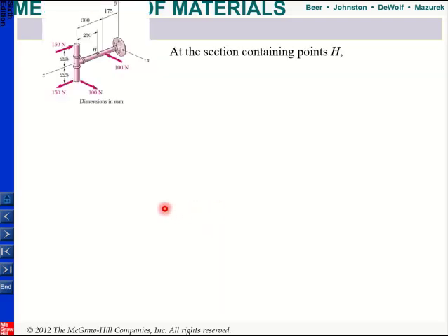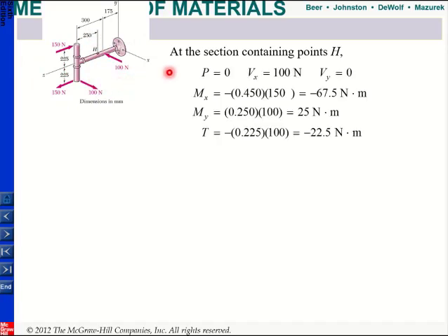All right. So when we cut at H, what you will see here is I have these two forces. They have the same magnitude but opposite direction, which means that basically they create a couple. Since this one goes counterclockwise, it will create a moment along the minus x direction. If you look at this one and move it there, this is parallel to x, so it will not create any moment along x, but it will create a moment along z, so it will be a torsion. Plus, it will also create a moment along the y-axis. If you find them, the two cancel each other, so there is no net effect at the centroid where H is.